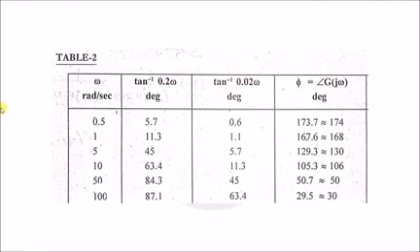See, the omega here in this phase plot is a smooth plot. The magnitude plot will be drawn using a scale, but the phase plot has to be drawn freehand. If you draw freehand and your values are near to each other, it will be a more satisfying plot. So you have to choose all the corner frequencies. With respect to that, if you choose some more frequencies, then you get a smooth curve.